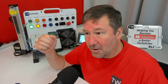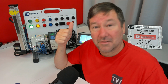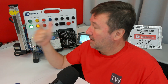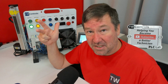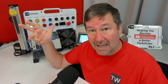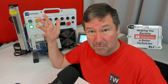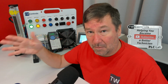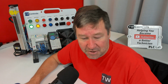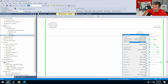But for the most part, the instructions that I see in most of your programs are the MSO, servo on, MSF, servo off, the MAM, motion axis move, the MAS, motion axis stop, and the MRP, motion redefine position. So we're going to talk through how we can make a program work with just those 5 instructions. And so we are not going to work in the sequence one that we did last time.